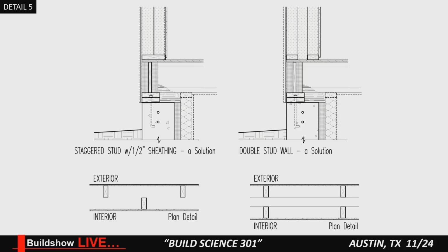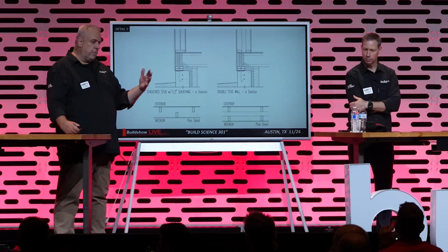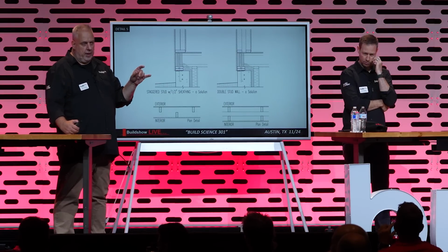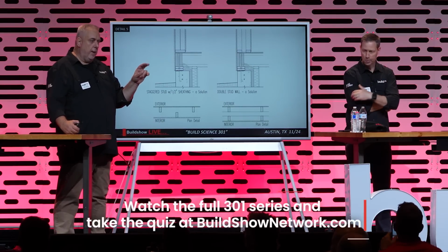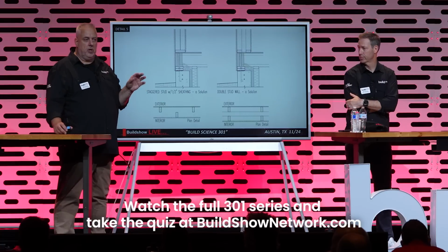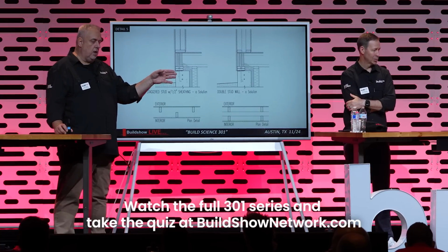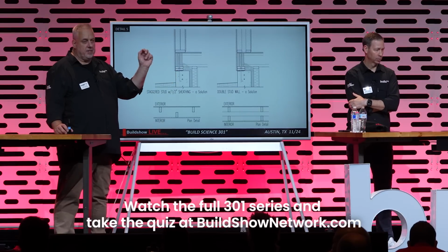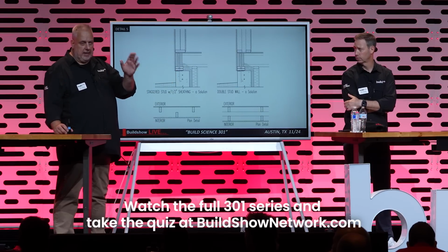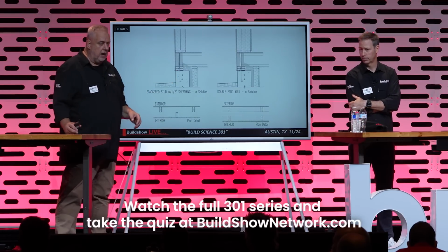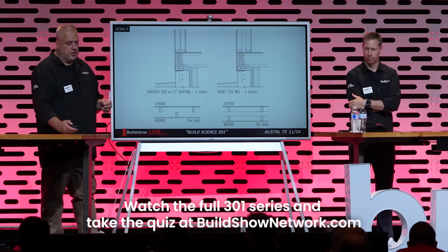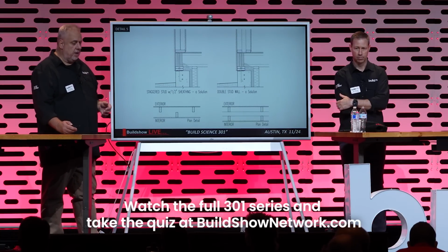Now, the thing you want to worry about, though, is that if you're not going to have total control of that condensing surface, we really want to be vapor open to the outside, right? So the vapor profile and insulation really play kind of a tandem role, buddy-buddy system, to ensure that we're either vapor open across the wall in the vapor profile, or I have insulation adequate enough to keep the vapor in the vapor state and not allow it to condense on a cold surface, right? And that's true for the double stud wall.